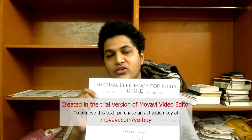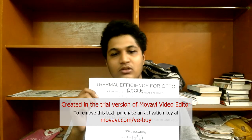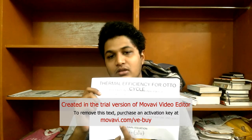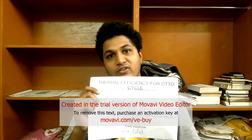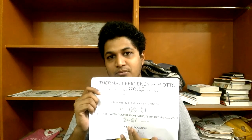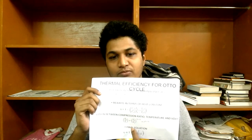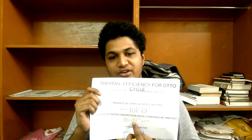So rewriting your equations in those terms is quite helpful. So let's carry on. As you can see over here, the ratio of temperatures can obviously be written in terms of a ratio of volumes, and because it is an adiabatic process, you also have your gamma involved over here. Because you have V1 over V2 given over here, this can be treated as a compression ratio.